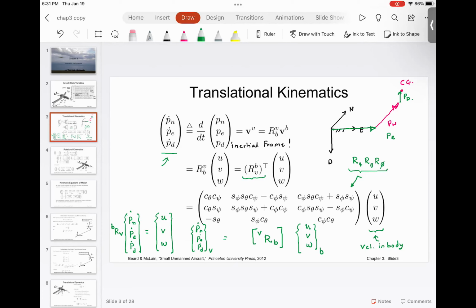However, there is a small problem, because please understand, this aircraft is not going to fly at the fixed roll, pitch, and yaw. What it means is as U, V, and W are changing, roll, pitch, and yaw will also be changing. So you will have to compute the resulting solution every millisecond, so that you have an accurate representation of the north velocity, east velocity, and down velocity. Everyone understood this?